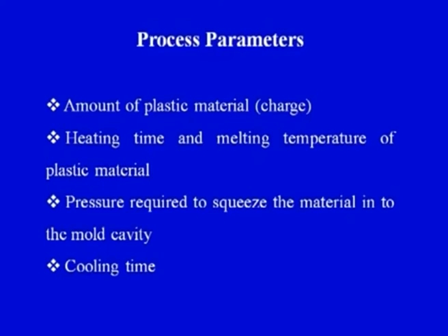And finally, once the material has filled each and every corner of the mold cavity, the two mold halves would remain closed until the final product is ready inside the two mold halves. So the cooling time is also very important. It is the time we allow the two mold halves to remain closed without any heating taking place, while the final product is cooling into the desired shape.